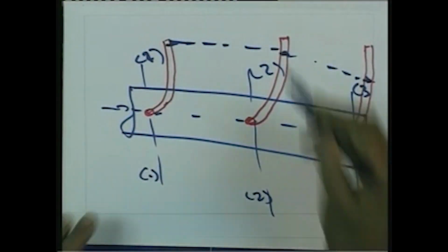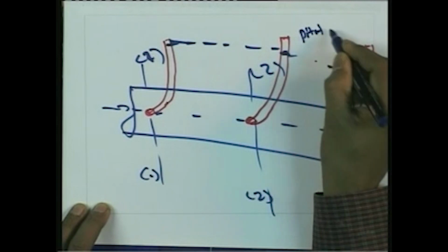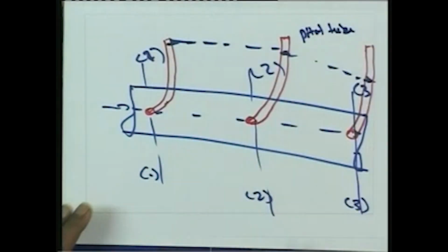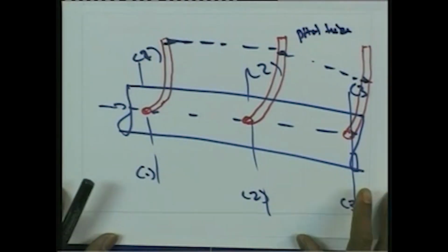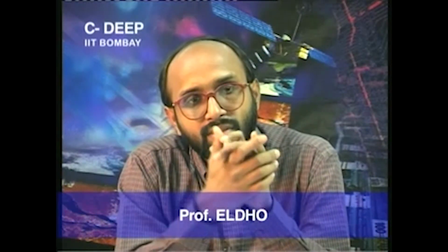So you can see in this figure, we are introducing the pitot tubes at various locations, and then we can finally get a line, the so-called energy line. These hydraulic grade line and energy line concepts are very useful, especially for pipe flow analysis and open channel flow analysis. Here again we are using Bernoulli's equation, or the total energy principle, the principle of conservation of energy.